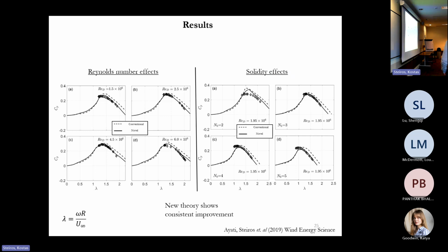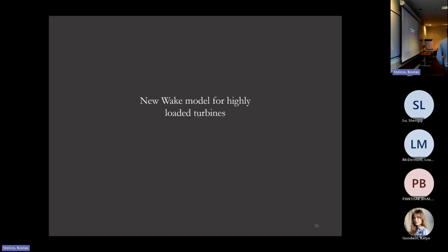And then they start diverging at higher and higher speeds, because the faster a turbine rotates, the more it resembles a solid plate or a solid disc, right? So the effective solidity increases. So this is where the new theory shows the best improvement, one can say. So that is quite a nice result from a theoretical result. We went to a more applied case and saw some improvement.